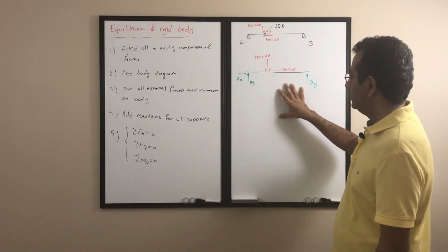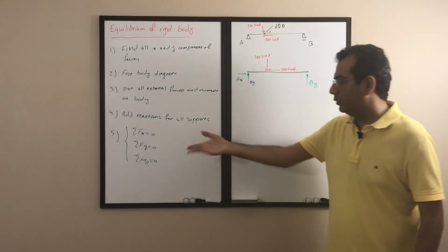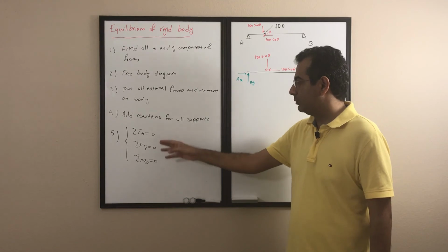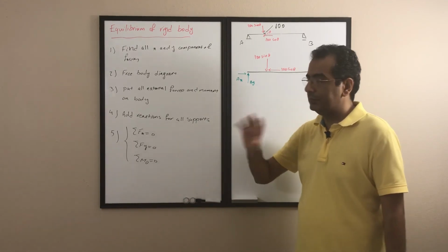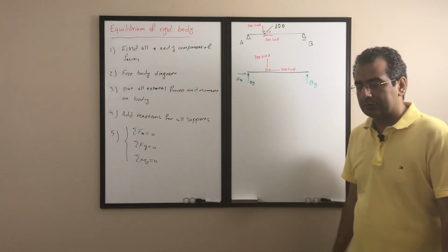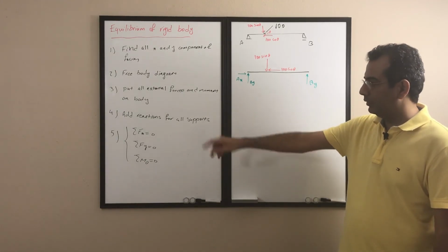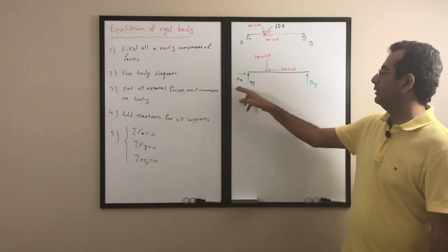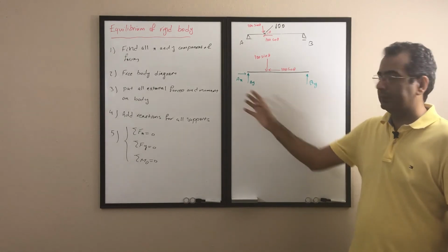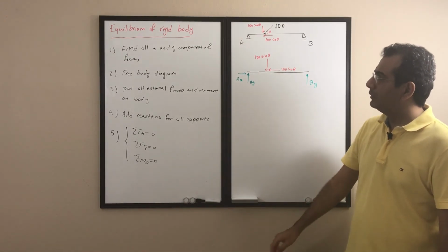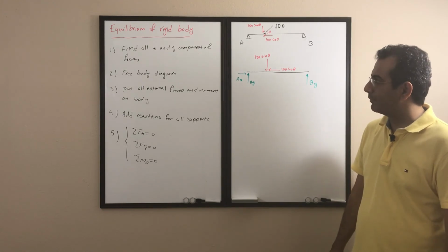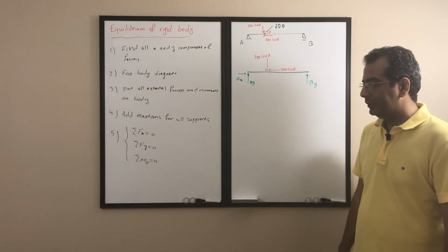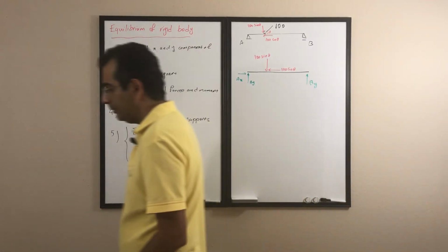After I get to this point, I just write these 3 equations in an order that works best for me. Remember, you may first need to use M or use Fy, depending on your problem. You can switch the order of those equations. So use these 3 equations to find the unknowns. For example, here the unknowns are Ax, Ay, and By, so we can find them. Almost all the 2D problems that we have work with 2D equilibrium. That is how we are going to solve the problem.